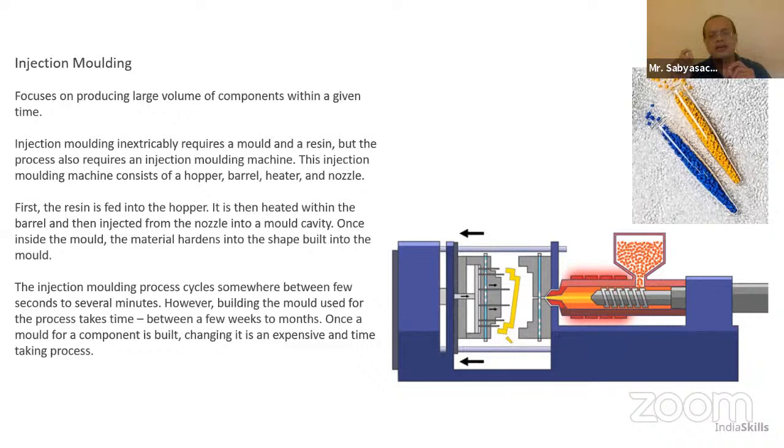For a commercial grade, the shrinkage is not exactly controlled. And here I'm talking of shrinkage in the range of about 0.01% or 0.1%, or maybe at the most 1%. So that is the kind of high degree of tolerance that plastics have. And then the mold opens and the component can be taken out, right?